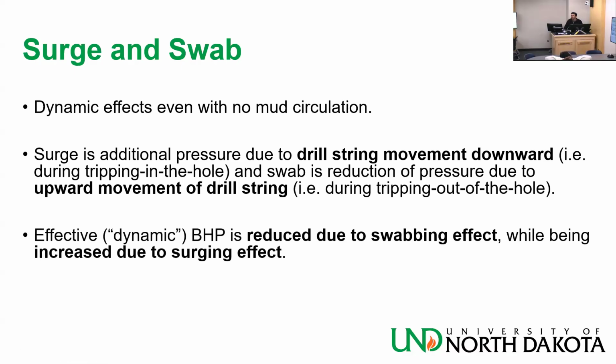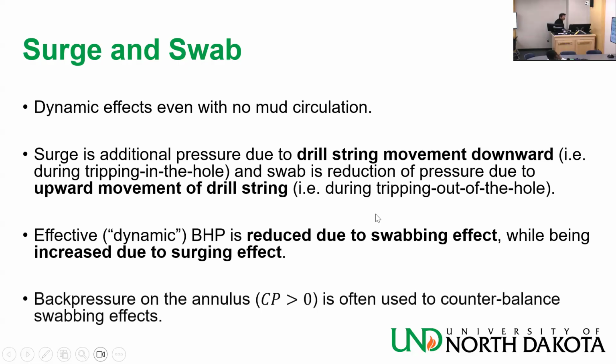So swabbing, think about it as a kick. Be worried about the kick because the bottom hole pressure is reduced. The formation is feeling a lower density than what it really is statically. And the surge is the opposite. You are worried about fracturing, because the rock is feeling a higher density than what it really is.